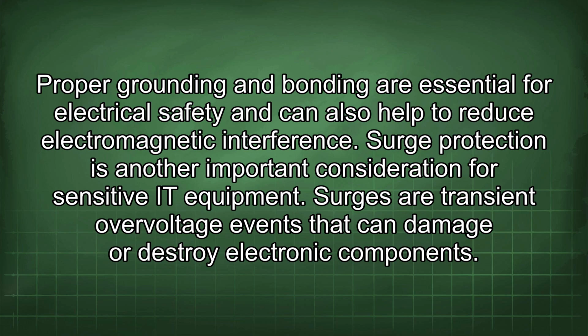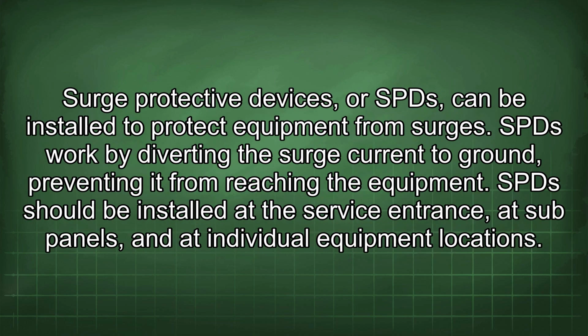Surge protection is another important consideration for sensitive IT equipment. Surges are transient overvoltage events that can damage or destroy electronic components. Surge protective devices, or SPDs, can be installed to protect equipment from surges. SPDs work by diverting the surge current to ground, preventing it from reaching the equipment. SPDs should be installed at the service entrance, at sub-panels, and at individual equipment locations.